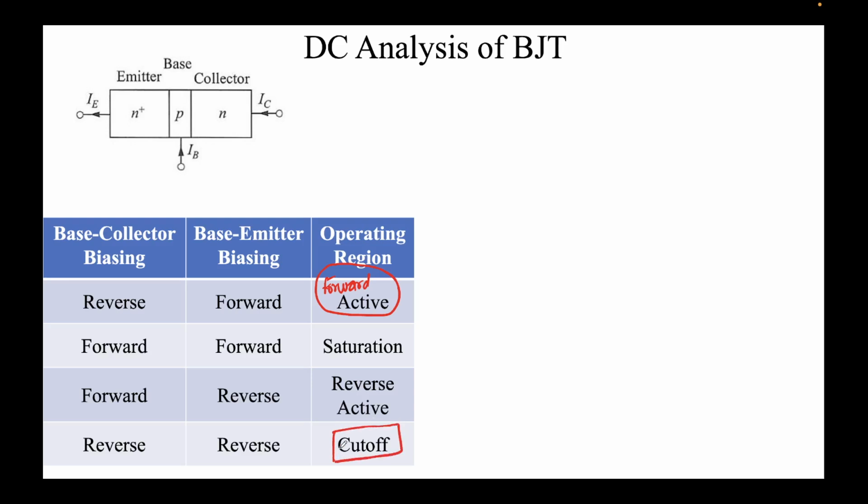In a more common term, we can say the device is off. Technical term is cutoff. This means no amount of current is flowing. And this cutoff state that I'm talking about is used as the state of a digital off. I talked about the digital on and off in the last slide. When we are in the cutoff mode, it essentially means the digital state is off, and for the saturation state, we say it's on.